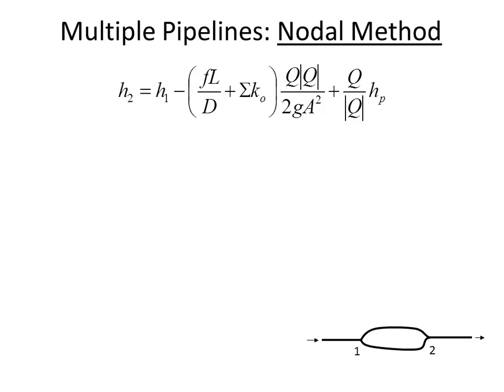In this equation, what it assumes is that water is flowing from junction 1 towards junction 2. And so the purpose of these absolute values in the flow rate terms that you see, instead of just saying Q squared, for example, here, they very intentionally had one of the terms be absolute value of Q and the other one isn't, so that if the flow direction is negative, you retain that negative sign overall.